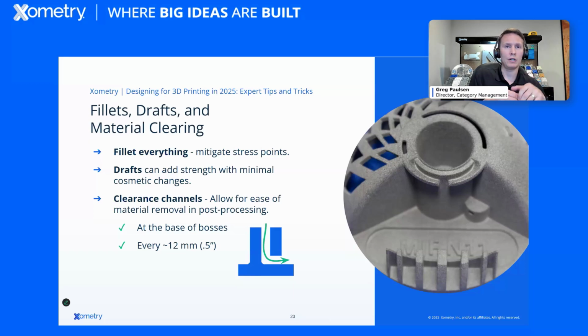And clearance channels are something that's really important for liquid-based processes as well as powder-based processes. I typically am post-processing with blasting, like I'm blasting beads down into these parts to clear them out, or I'm using a water jet or something to get out that material. If I have a blind boss, a screw hole that just ends there, it has uncured or unsintered material within that. If I'm trying to blast it out, all I'm going to be doing is packing that material down to the base, and I may need to use a toothpick or something to help clear that out.